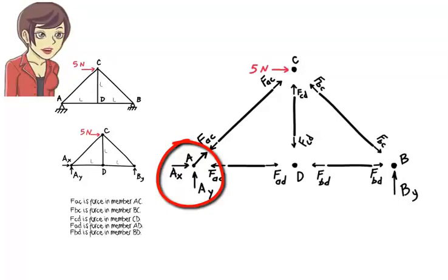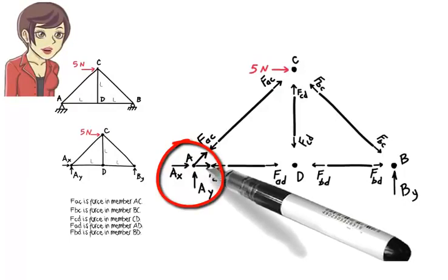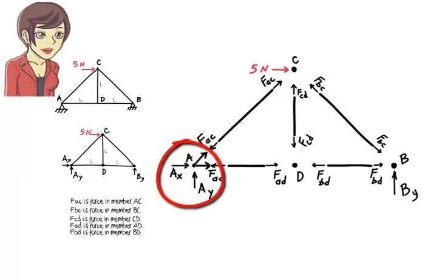This is the case because the two forces must cancel each other out. That is, if we reconnect member AC to joint A, the sum of the internal forces must vanish. Obviously, this happens only when the two forces are kept in opposite directions so that they cancel each other out. There is one more member force acting on the joint, the force in member AD. Again, we place this force at joint A in a direction opposite to how the force is acting on member AD.